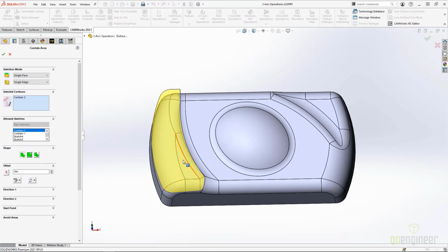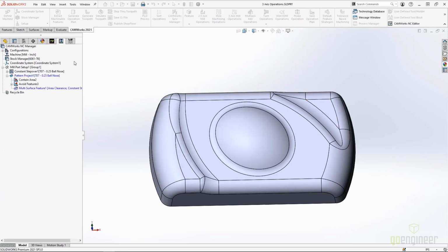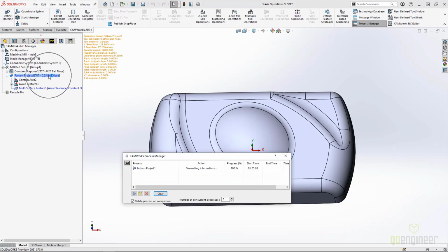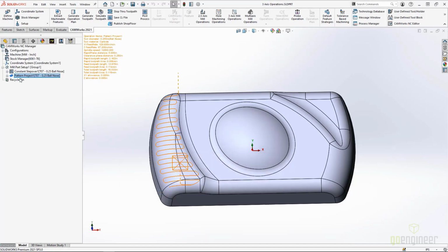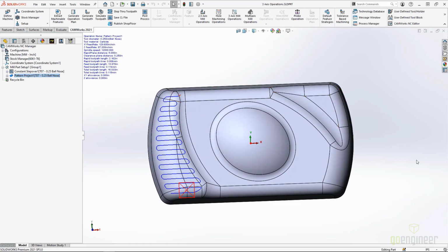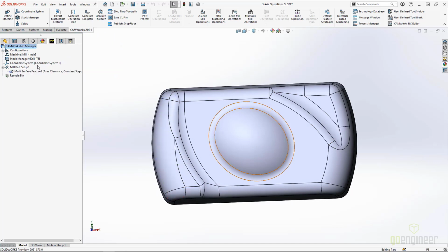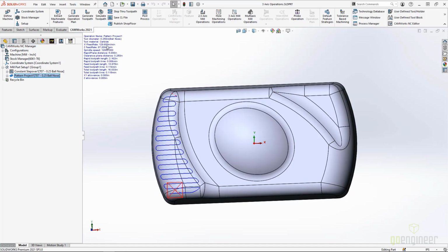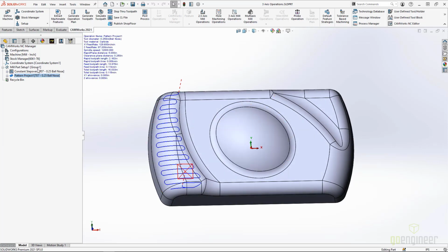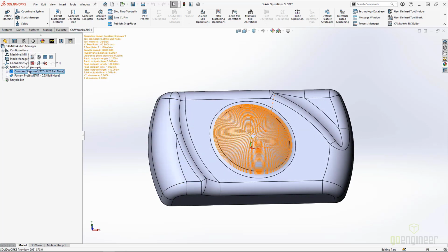I'll use, and again, I've just predefined some sketches. We could use the geometry of the part as well. I'll just generate the toolpath with the default settings here. So essentially I could go through and machine this entire part just utilizing one feature and contain and avoid areas. The other thing that can be helpful is using our control key to be able to copy an operation.